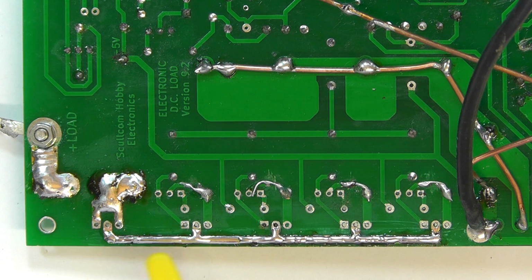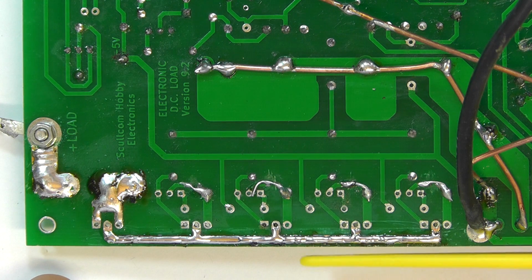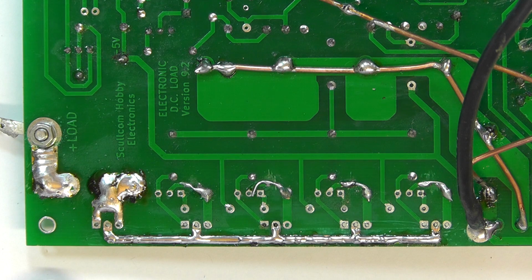And the only thing you need to be careful of now is that when you're bolting the board itself onto the case, make sure that you've got a space between the edge of the board and the heatsink. So you need to have maybe a millimetre or two space between the edge of that board and the heatsink itself, so that it doesn't short across to the heatsink.